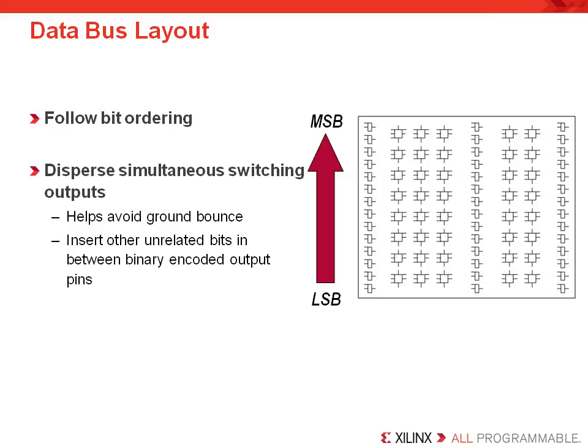In Spartan 6, we can also have I/O pins on the top or bottom of the device, but since carry logic is the same, designers should plan on assigning timing critical pins to the pins on the left and right edge of the die. This will shorten the associated routing delays and improve your I/O timing. You should also remember that the carry logic resources are inferred automatically by all synthesis tools, so you should plan your pin layout as I have just described.